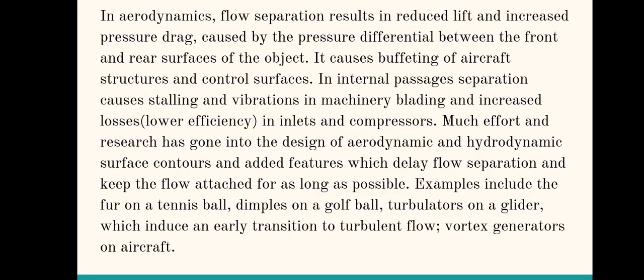In aerodynamics, flow separation results in reduced lift and increased pressure drag caused by the pressure differential between the front and rear surfaces of the object. It causes buffeting of aircraft structures and control surfaces.